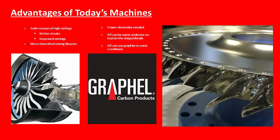Automatic tool changers. You can get anything from a 4-position shuttle changer on a small sinker to however many positions you need on a major tool robotic system. I have seen shops around the country that would have as many as 12 to 14 or 15 fully automated Sinker EDM cells, where a robot will actually feed blanks of graphite to a mill, take it from the mill, and feed it to the sinker. So the milling machine is making the electrodes. The robot is feeding those electrodes to the sinker machine to make the parts. So lots of advancements like this.